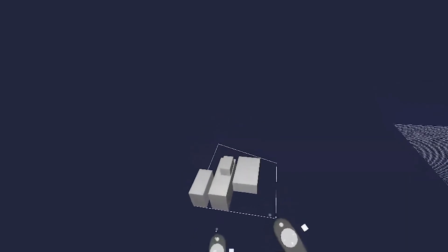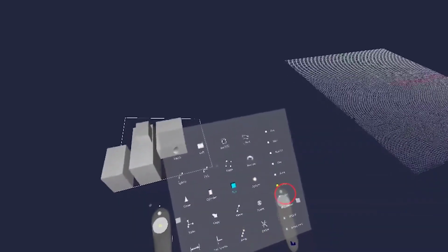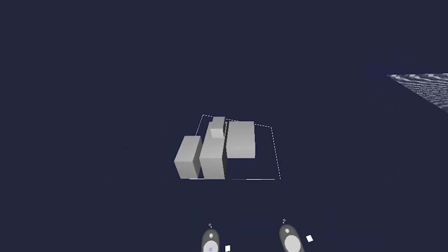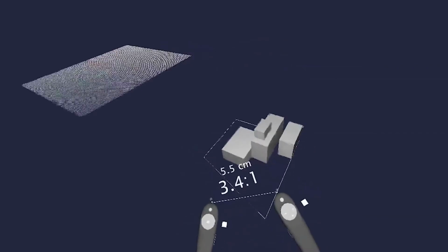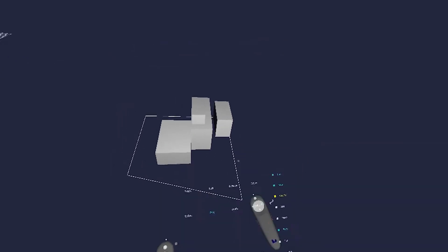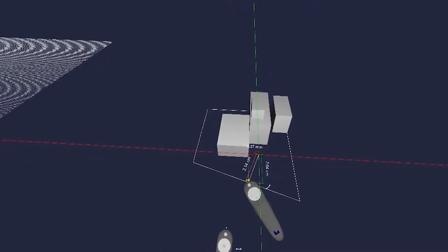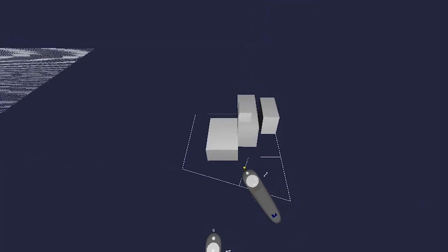Another similar snap is the perpendicular snap. This is really helpful when you have geometry that is not all rectilinear. So if we go ahead and spin around to the back side of the block, and also turning on the near snap for our convenience, we can go ahead and click a shape that is perpendicular to the angled shape. Notice this is 90 degrees right here.